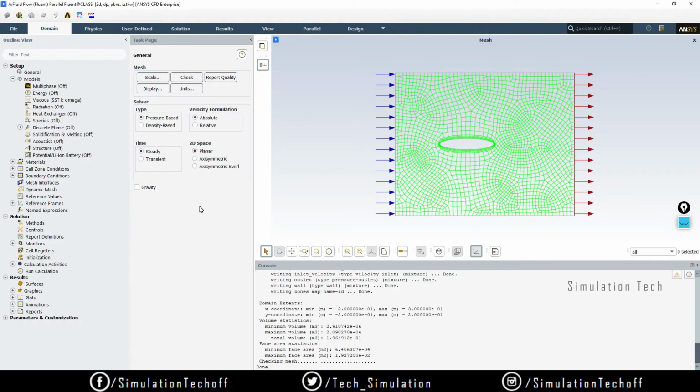So if it is a liquid, for example a liquid flowing in a pipe section, we can't compress that liquid. Okay, so for that we will move on to the density based one. At most stages, like 80% of the problems will be based on the pressure based one only, and only 20 or 15% will use the density based models.